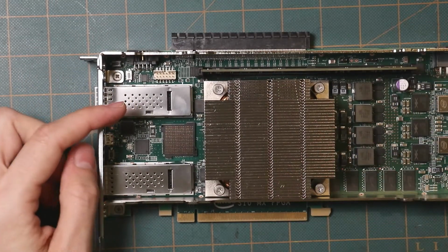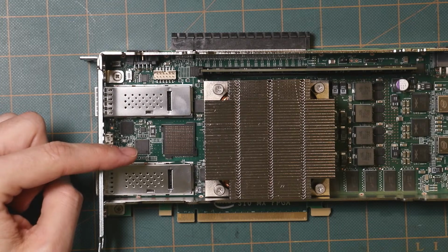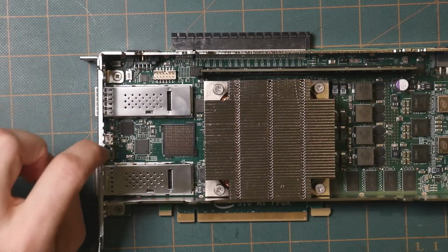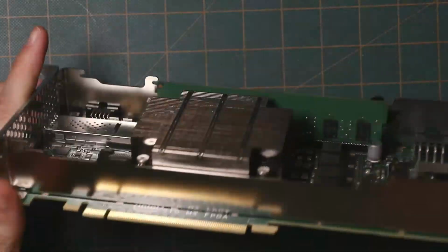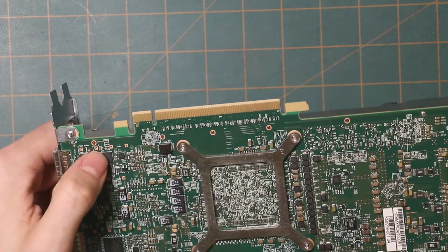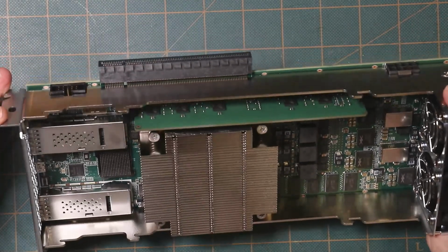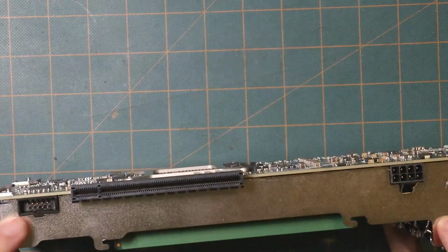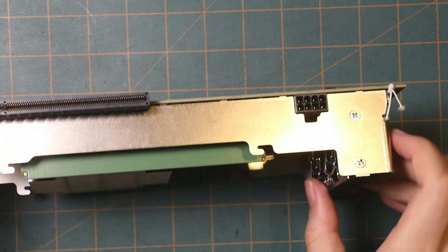All right, what have we got on this side? We got a pair of the QSFP modules, and then we've got a Silicon Labs chip here for clocking, and we've got a Cypress chip for the USB. So that chip plus the Max 10 is what's going to give you the USB JTAG. Oh, and then there's a config flash over here, I think. I believe this is a QSPI flash chip for the FPGA. And there may be another flash chip for the Max 10. Not sure about that. JTAG connector here, if you want to plug in a bit blaster or a USB blaster. And then there's a power connector here.